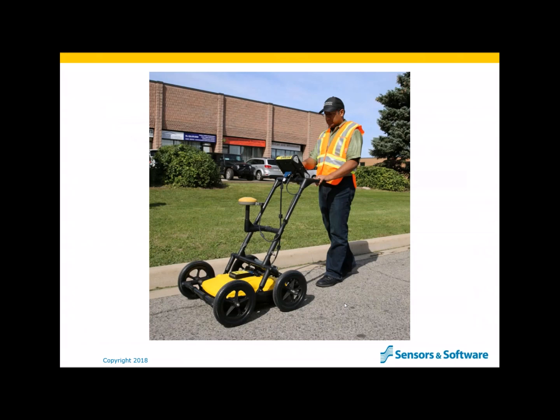So what causes coherent system noise? It is caused by poorly placed metal cables or metal housings that get energized when the GPR transmitter fires, and, similar to what we saw with the shallow metal debris, re-radiates the GPR energy. These signals appear in the GPR data usually as banding.